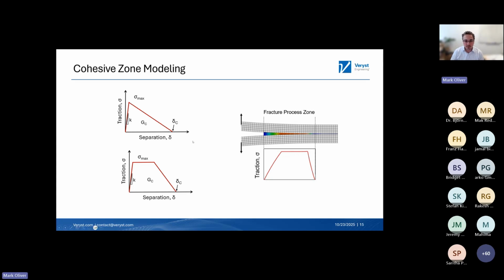And so for this kind of trilinear traction separation law, this is what we often plot, traction against separation like this. But if you are modeling an adhesive being loaded to failure, there'll be a leading front at the crack tip here, where things are starting to be loaded elastically. And then as you go further back, there's a region of constant stress, and then the stress decays out to some point here, where beyond here, past the crack tip, you're not carrying any stress. So you can think this is the crack tip here, and this is the start of the fracture process zone.